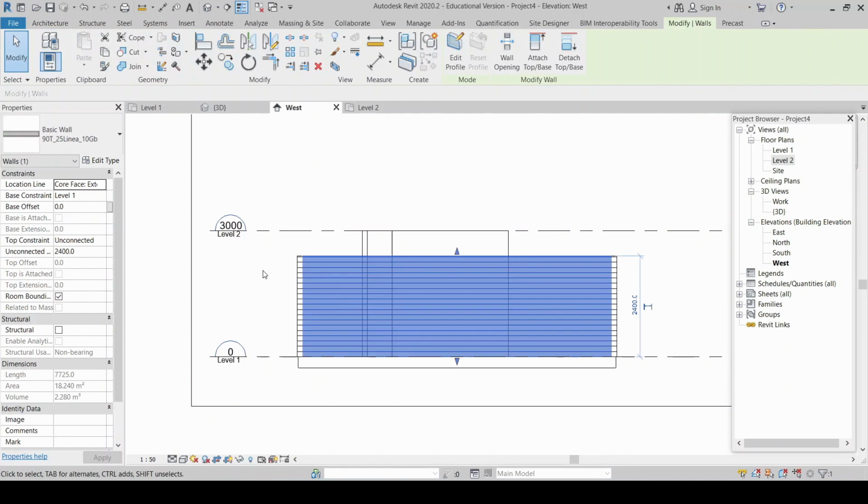I talked when we were generating the walls that we can actually connect them automatically to a floor level above. So once we've got a wall selected, or multiple walls selected, you'll notice in the properties panel, where we were changing the height of the wall, immediately above that is the word unconnected, and that's the top constraint of the wall. If we drop down the menu, now you may be wondering where the drop down is. You can't actually see the drop down in this little panel. You'll learn where they are, but if you do click on the box, you'll see there's a drop down. Drop that down, and we get the 3 options we have available.